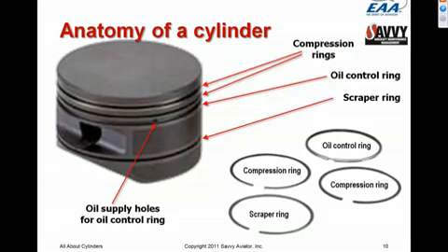Each ring is about 80% effective in doing that. So by stacking 2 rings in tandem, you get a seal that has efficiency up in the high 90% range. The 3rd ring down is an oil control ring.